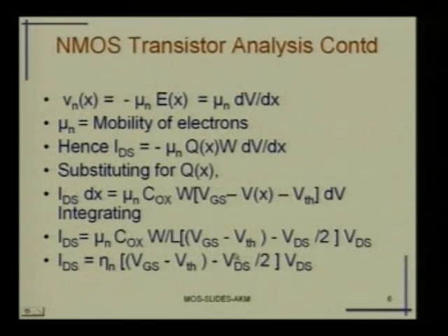Now, look here, the current, again I repeat, VDS under the condition that VGS is greater than VT, the threshold. Otherwise, the current is 0. As you increase beyond the threshold, the channel is established, and now this expression is somewhat quadratic in nature, because of VDS square and times VGS minus VTH. If you assume that VGS and VTH are constant, which is the case, and then VDS square, this term, if I neglect it, VDS square by 2, then this becomes an ohmic equation.